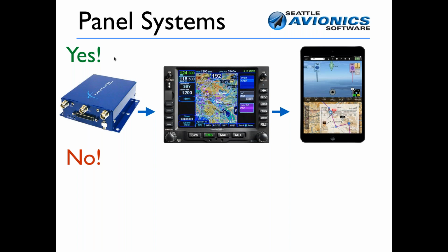Basically the ADSB signal goes through the Avidyne. The Avidyne's Wi-Fi then includes all of the positional information and the AHRS information that the Avidyne is broadcasting. It also tacks on all of the ADSB data it gets from the Freeflight system, sends it to FlyQ as one package, and you're good to go. You'll get traffic and weather and all that good stuff, and be able to transfer flight plans too, by the way, with the Avidyne.